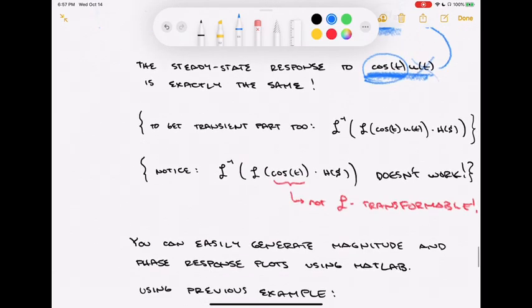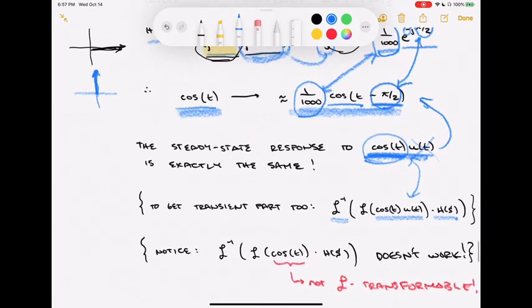You could, if you wanted to, try to get the transient component for this one. If you were going to solve this in its exact way, what would we do? Maybe I would Laplace transform my input, multiply it by the transfer function, because we can multiply in a transform domain expression. That saves us a convolution. And then I could inverse transform it. So if you really wanted to see all the terms in there, you could do it this way. And what you would find is you would get this piece, and then you would get some other pieces that have some decaying exponential components.